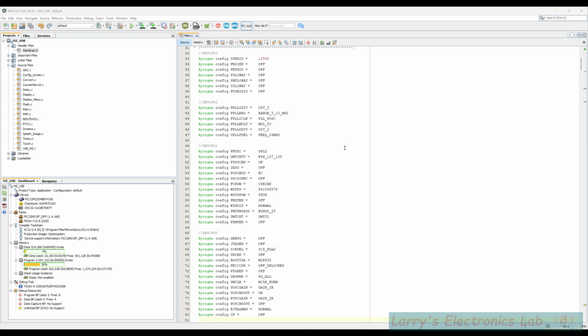I believe the 144 pin has everything, but I'm not sure. On the 100 package I use here, there are a couple of modules that have no pins coming in or going out of them. So you have to use the PPS mechanism to program some IO pins for your module.